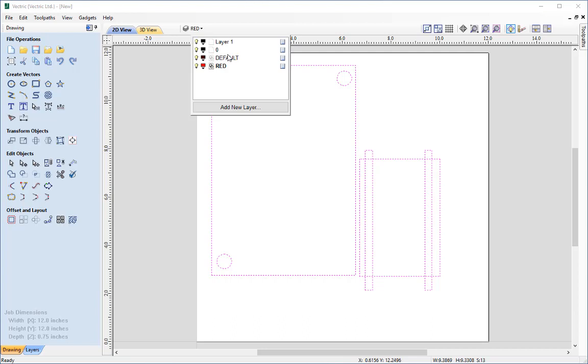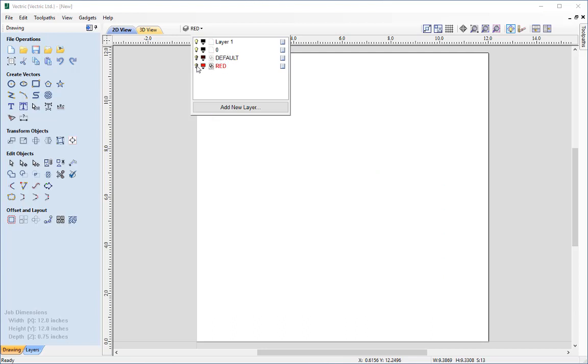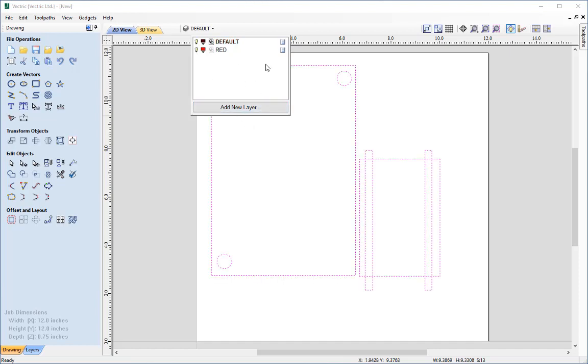And in a large job where we've got quite a few layers with no information on them, we want to have an easy method to actually delete all those at once. Now an easy method to do this would be to just turn the visibility off of the layers that have vector information on them, just leaving the ones that don't visible, like so. Simply click on this icon here, select the merge visible, and that will then place all those layers into just one layer, and then all we need to do is right click and press delete, and it will automatically just delete those because it knows there's no vector information on that layer. And then we can just go ahead and turn back on the visibility of those layers.